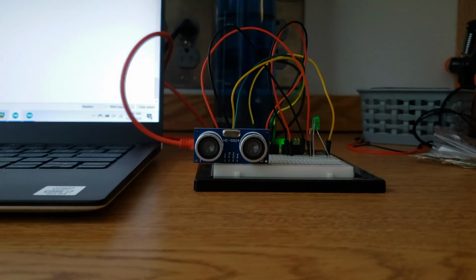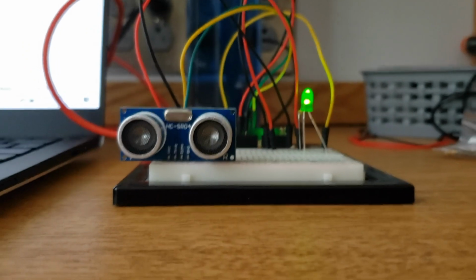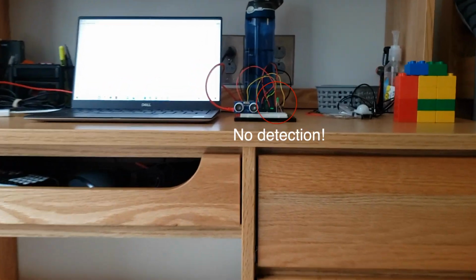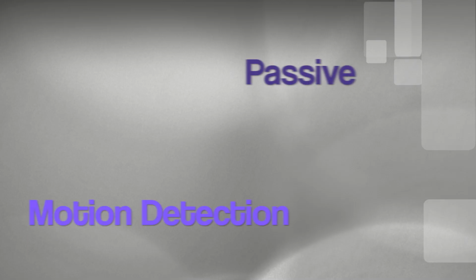Now, some advantages of active motion sensors, such as the ultrasonic one, is that it is a pretty simple and cheap setup, as you can see with our example here. And velocity detection can actually be somewhat accurate with these sensors. However, some weaker sensors can have difficulty at further distances, and it really only provides a pretty simple analysis of motion. Also, ultrasonic sensors can be quite susceptible to false detections. However, playing with the minimum velocity threshold required for the signal to fire can help counteract this.